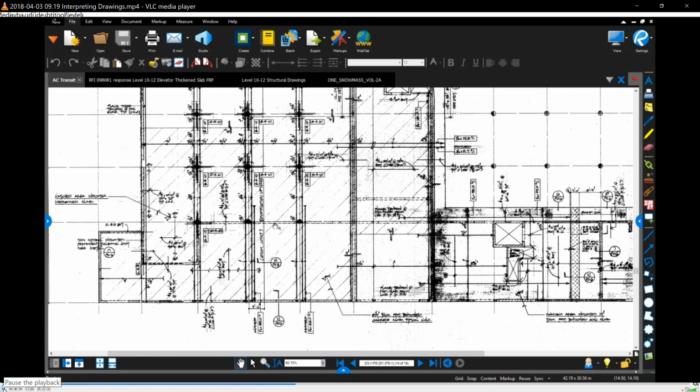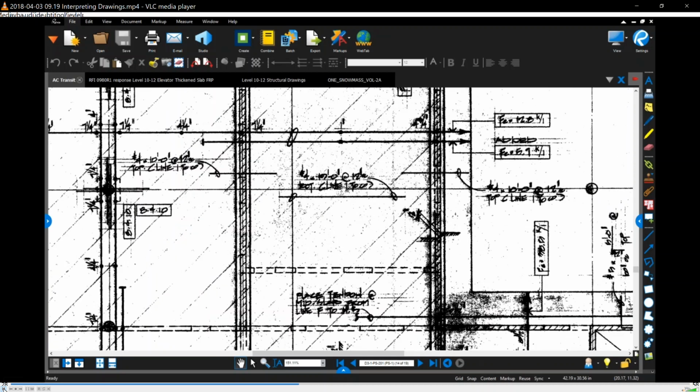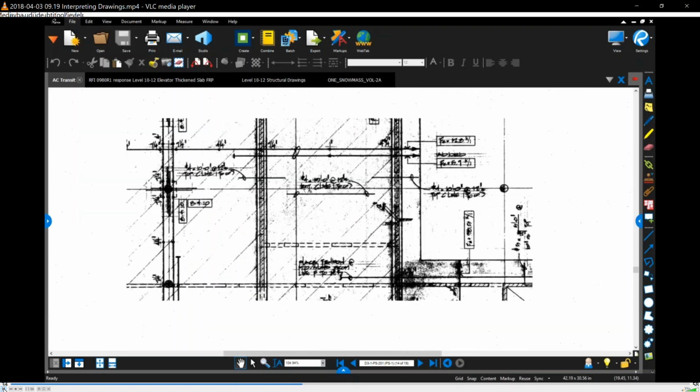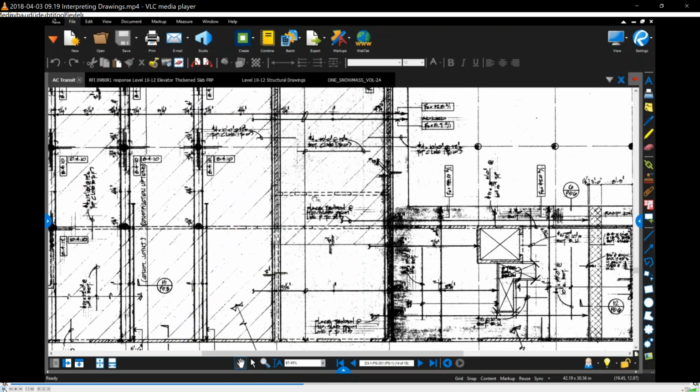So anyway, I know it's not FRP related, but I think it's helpful for when you guys are looking for particular rebar for an element. Here's some bottom bars. Number 4 is 19 feet long at 12 inches on center, bottom, so then they get the limit line on where that is. Do you guys understand when it's circled like this, and then here there's an arrow? All of those elements are spaced equally for that entire width, yeah.